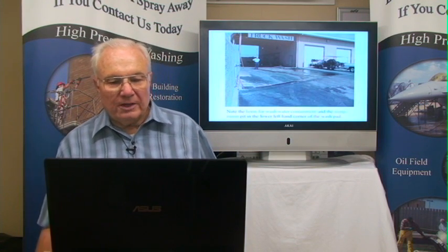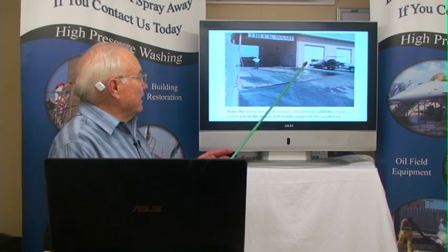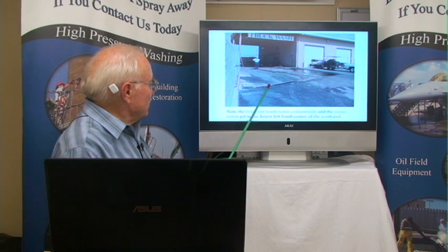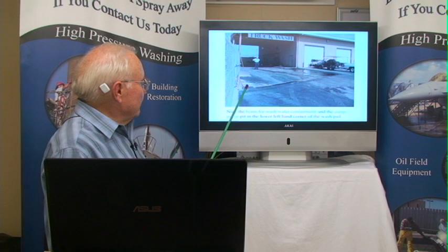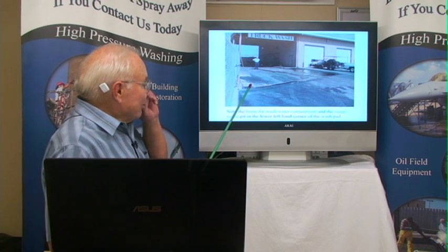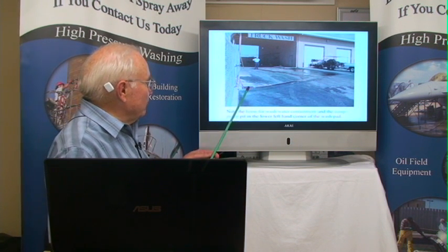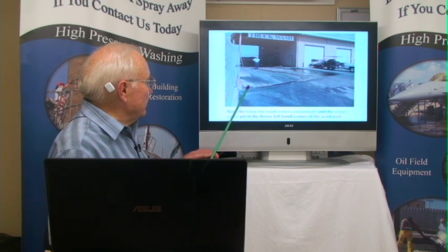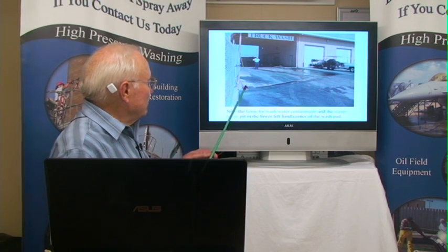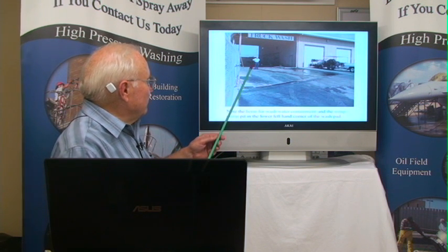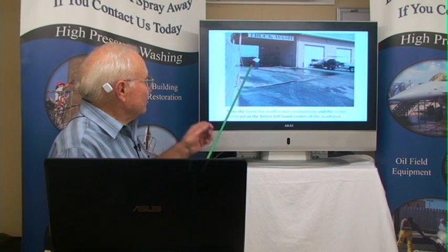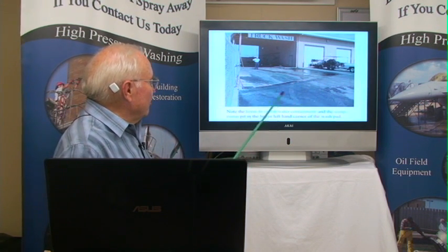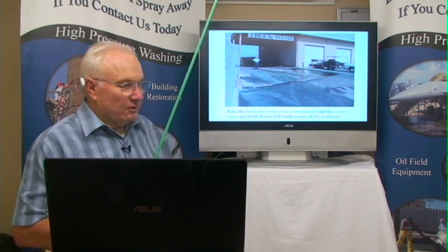This is a truck wash bay, and what they've done is run a berm right here, if you look, and then they got the drain there. That's actually not a drain. That's a drain, all right, but it only goes down. It's about a 10-gallon, maybe 15-gallon drain with a sump pump set into it. It pumps the water up to the sand trap in the middle of that bay. This has recently been expanded to an all-concrete surface instead of asphalt.